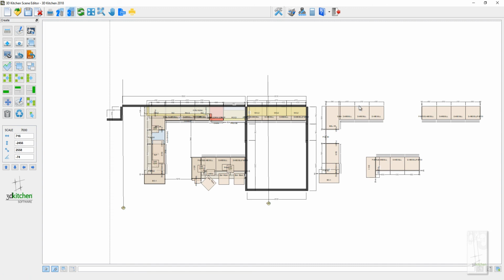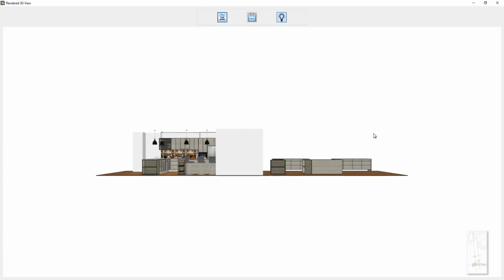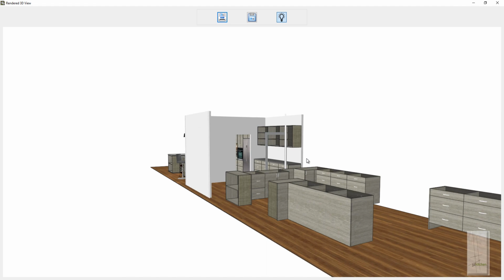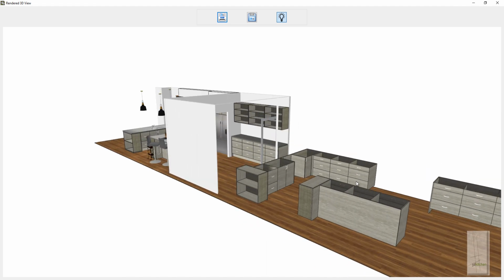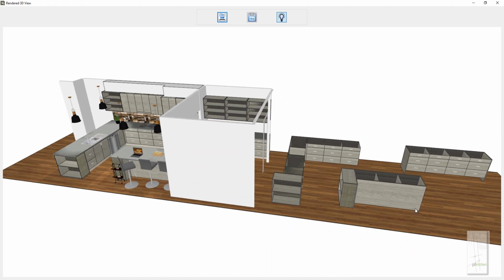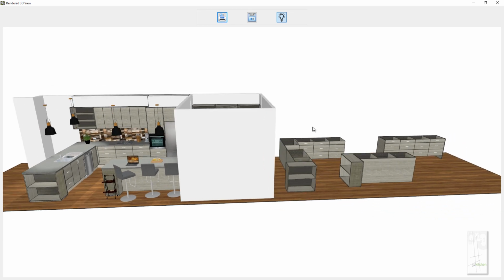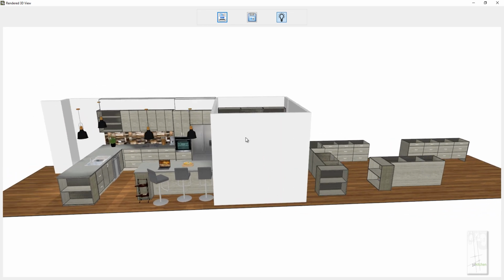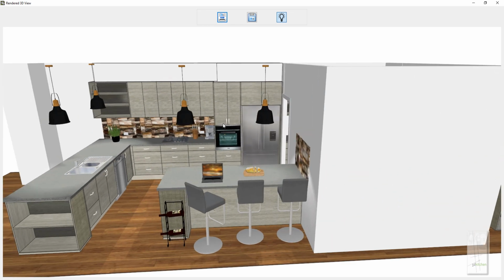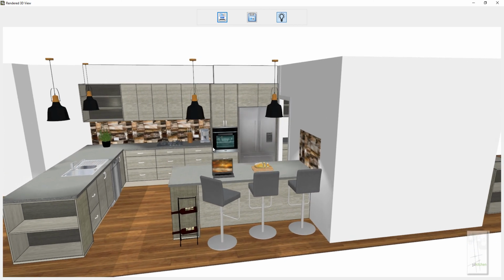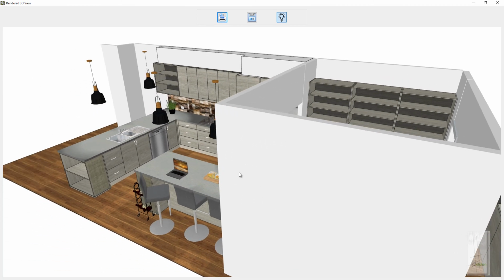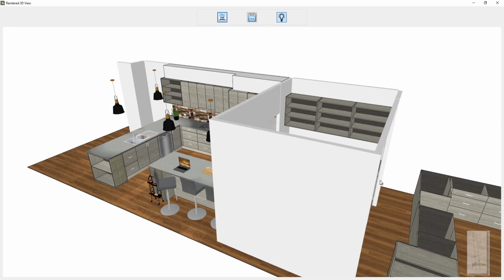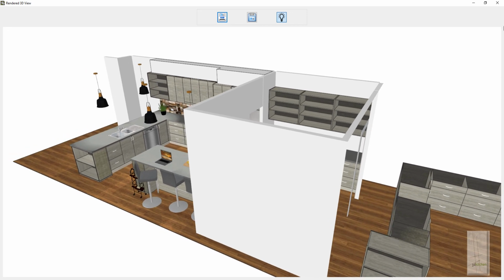Okay, so you can see now when I regenerate these objects that the ones that I've picked up have all stayed relative and they've moved out into this position. Now, they don't have to be like objects, they can be all different categories of objects. So whatever is selected can be picked up, moved, rotated, snapped to other objects very quickly without having to combine them.